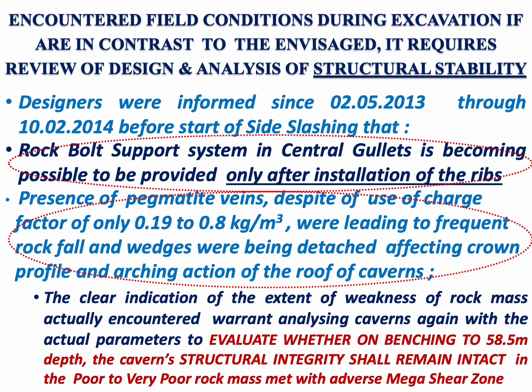The clear indication of the extent of weakness of the rock mass actually encountered warranted analyzing the caverns again with the actual parameters, to evaluate whether on benching to 58.5 meter depth the cavern's structural integrity would remain intact in the poor to very poor rock mass met with the adverse mega shear zone.